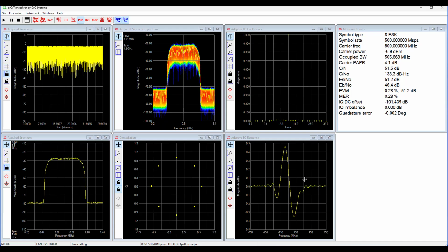Here's actually the frequency response of these tap coefficients. And you can see in this case, again, this is non-symmetric. Below the center frequency and above the center frequency, they're not the same, and that's what we get when we use complex valued FIR filters.